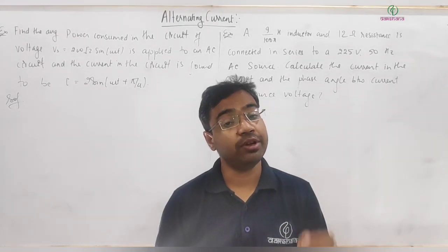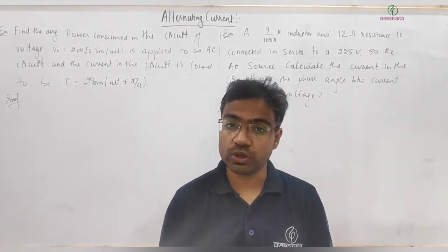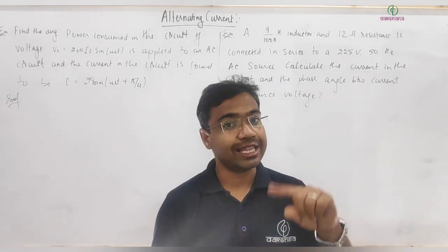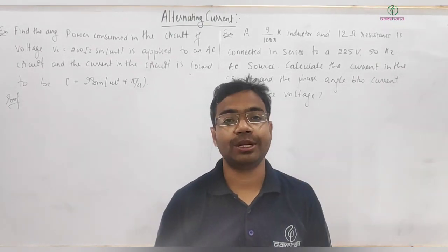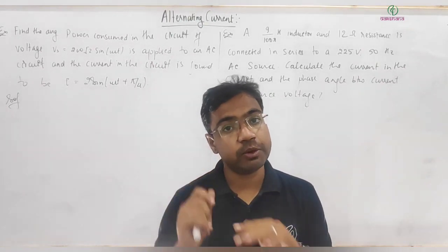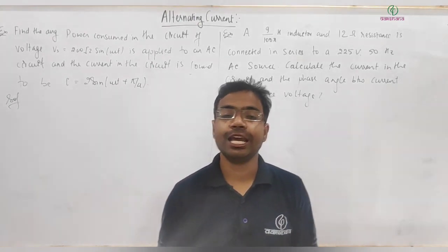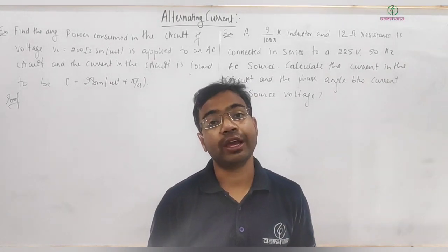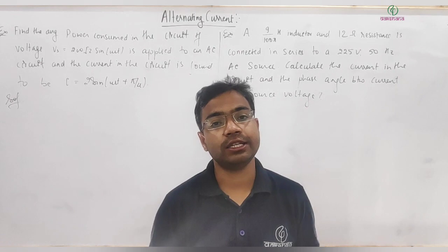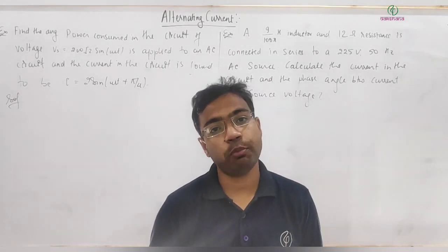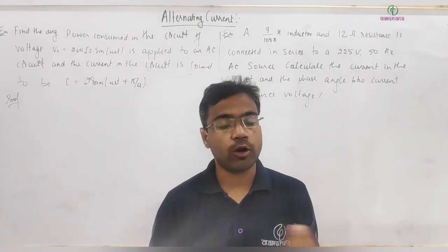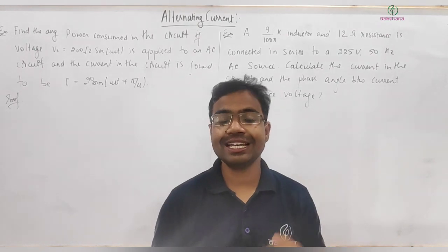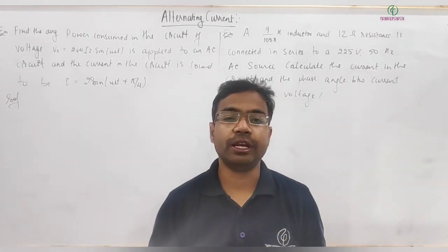Try to draw the phasor diagram. Regarding the phasor diagram, the quantity which is along the x-axis should be constant across all elements. In a series circuit, current is constant, so we should consider current along the x-axis. Similarly, for a parallel LC, RC, RLC or any other parallel circuit, voltage across each element will be constant, so we should consider voltage along the x-axis and then the currents. Based on that we will get the impedance and all that.